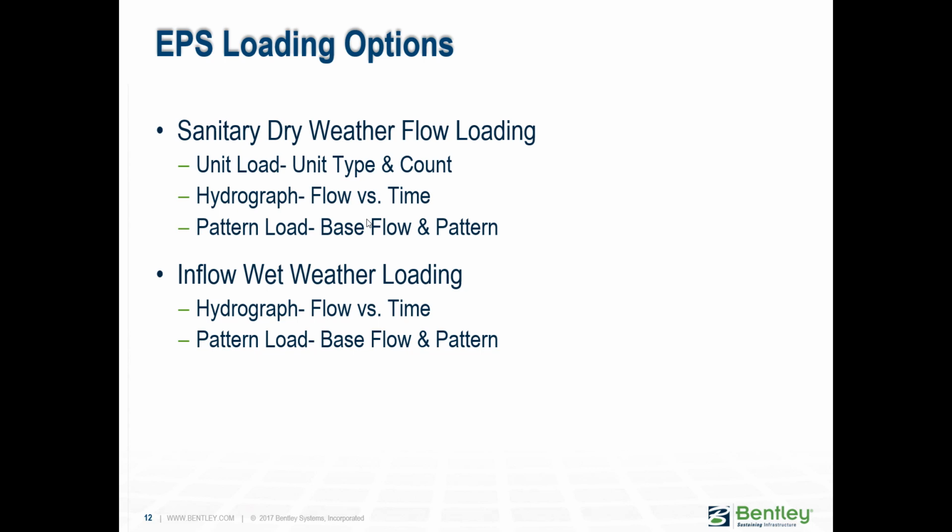Okay, so what options do I have for entering loads in an extended period simulation? For sanitary loads, you have these 3 options: unit load, hydrograph, and base flow and pattern. Unit load, you guys used it yesterday. So how many customers per hotel, for example. In hydrograph, you're actually entering flow.